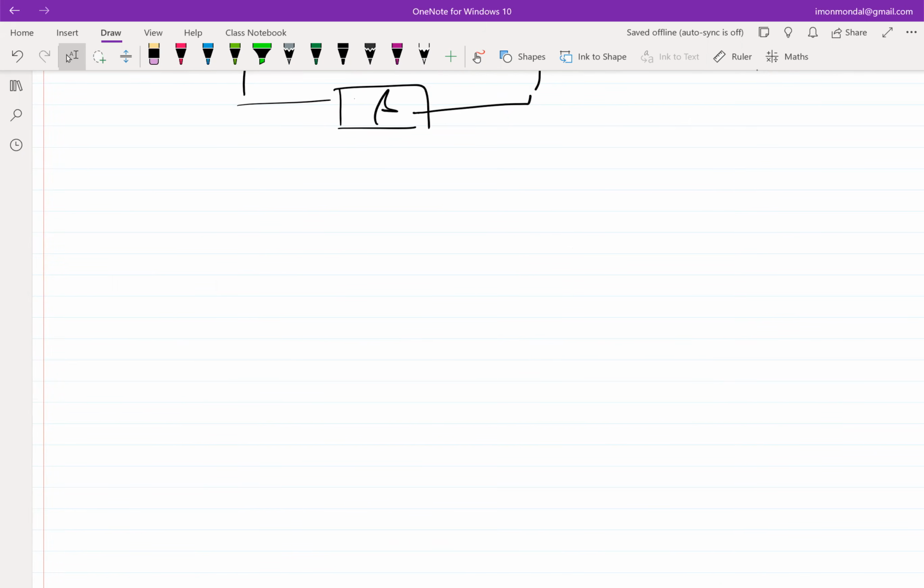So we were trying to look into that configuration where we want to observe the source and feed back the information at the gate, right? When I say observe the source, which means the constant current source is applied at the source, and I want to feed back at the gate, right? So the gate is not constant biased anymore, right? Now let's argue.